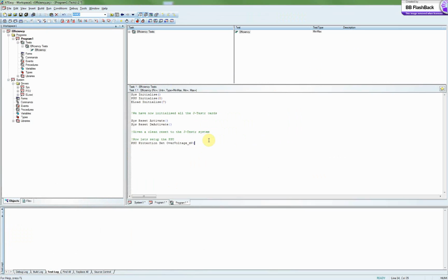So what you saw when this over voltage popped up, over voltage in millivolts, you saw we got a list of supply A, supply B, or supply both. That's both supplies. We will just set up supply A. So we will set up supply A for 12.5 volts. That's 12,500 millivolts, because this is obviously pre-appended with millivolts. So that set up the overvolt protection.